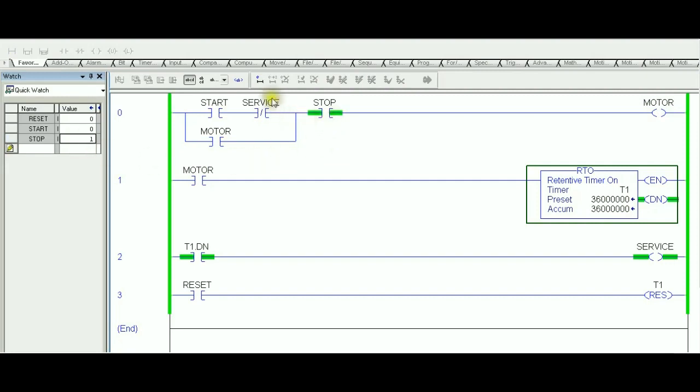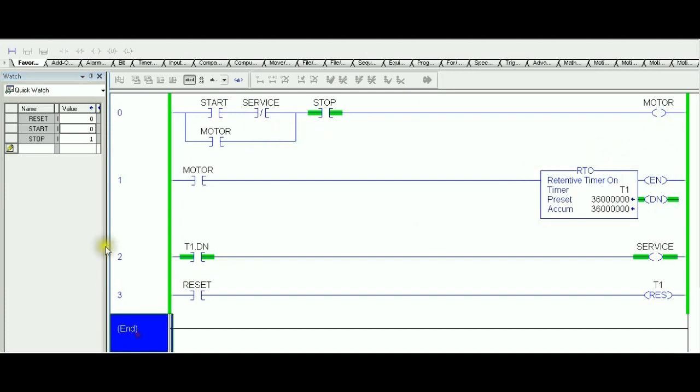Okay, but as you can see, the permissive condition we have added is false right now. So if I try to press the start, you see this condition is creating a gap in our rung and the motor cannot restart. Again, it depends on the application. If the requirement is that you want to lock an output, that's a common way to do it. So right now, the only way in this architecture that I can actually trigger the motor one more time is by hitting the reset first.